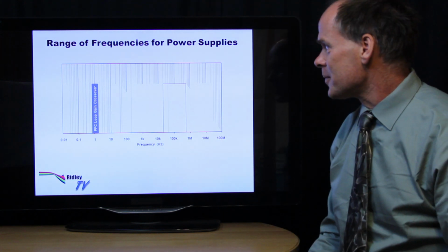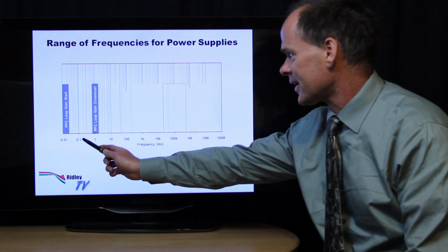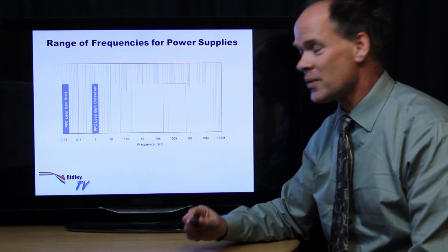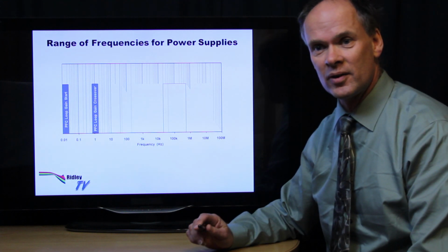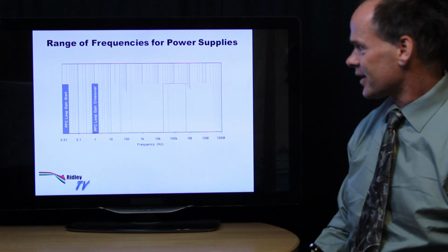Now if you want to see a loop gain associated with the power factor correction circuit, you're going to have to go either 1 decade or 2 decades below the crossover frequency, and that's where you're going to start your loop gain of your frequency response analysis. So that's the power factor correction circuit.